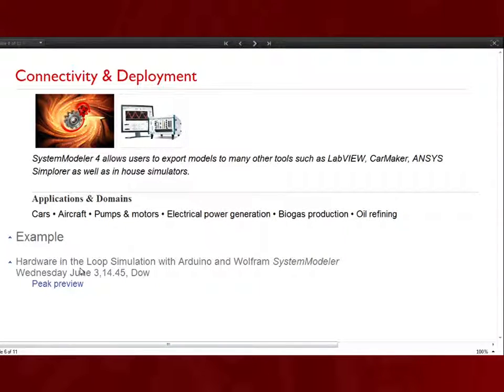But basically, I was planning to open a model where I will show, for instance, how to run this guy and control it from a model. So we will have the control system developed in SystemModeler and run this model where we will be trying to balance this ball here. And this is thanks to a new library called ModelPlug, which is a free additional library. And with that, you can create your own experiments like that easily.